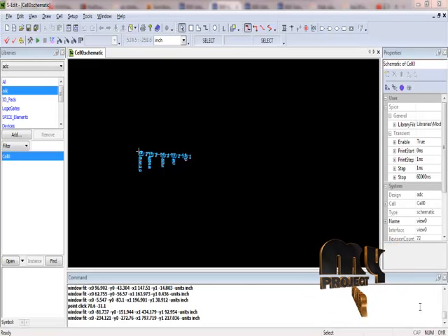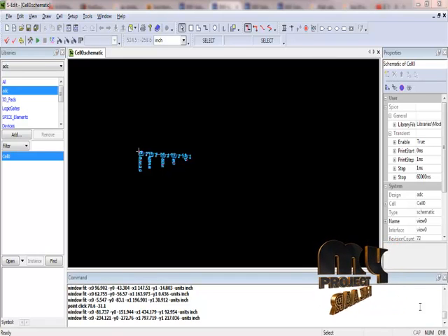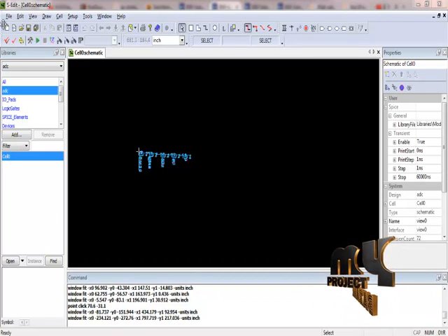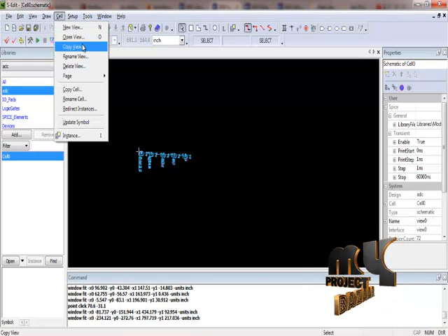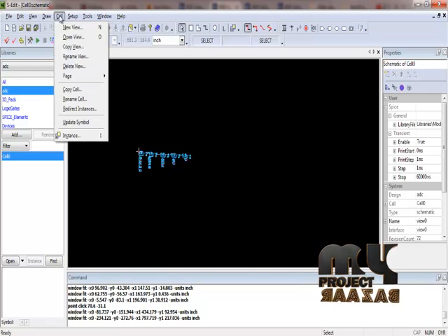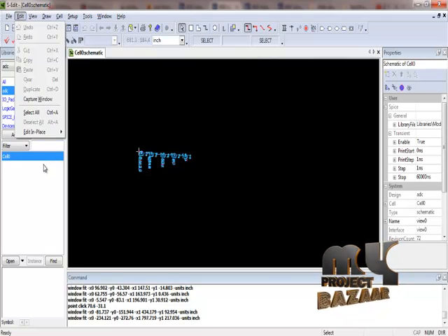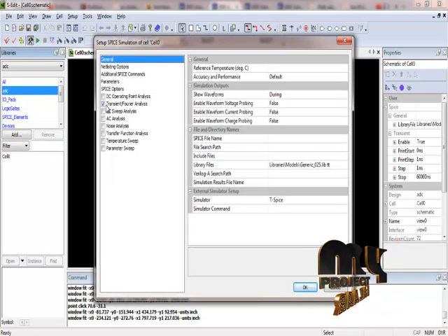Let me show our process running procedure. We have designed the ADC in Tanner EDA version 13, in a cell called cell 0. First we create a project, and then we design the cell. We have designed the ADC in cell 0, and then we set up the transient and Fourier analysis.